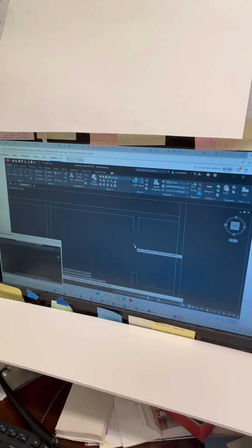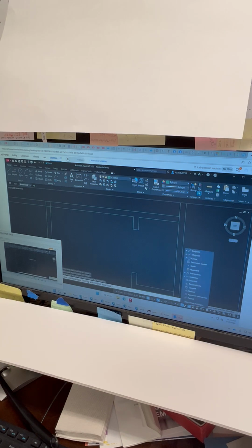So who is that, Patrick? Patrick, yeah, you're down at the bottom. Yeah, down at the bottom, it's actually on, but here, I know what's going on. You might not have set midpoint. That was one of the ones that I suggested everybody did. So click on that little menu there and select midpoint. Yeah, this was left over from yesterday, sorry. So go ahead and start the line command. Yeah, you got it. Now you can go to midpoint, correct.